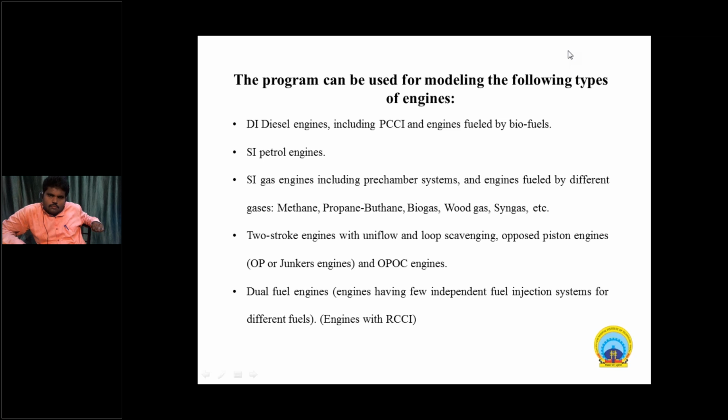So in this, the basic NOx calculation is very important for the Diesel-RK model. So in this there are 199 reactions and 33 species equations also. For the emission point of view, the soot formation calculation sub-model used is one of the most important parameters. So the ignition delay period is estimated using relevant data in the pre-calculated comprehensive 4D map of ignition delay. This 4D map is developed using Chemkin detailed chemistry simulation.